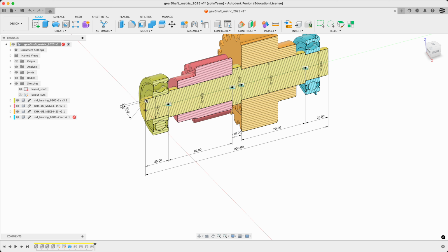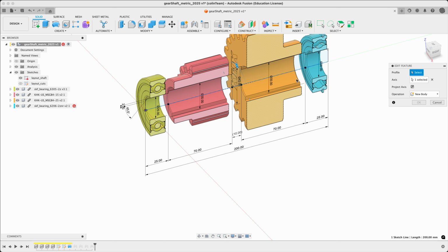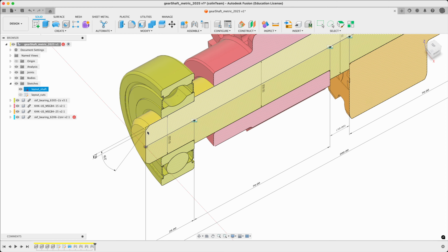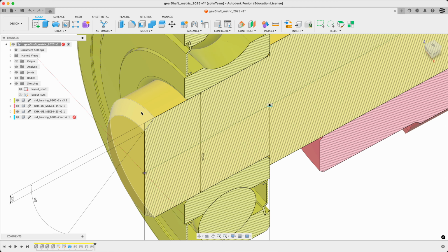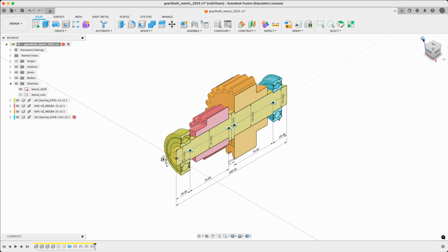One thing missing is the chamfer. The easy way to fix this, just select this thing. Profile, you'll notice has added the two little triangular profiles. Just X that thing and re-add it. Say okay. That should not cause any errors, but it does activate the chamfers. Perfect. There we go. That's our shaft shaped.